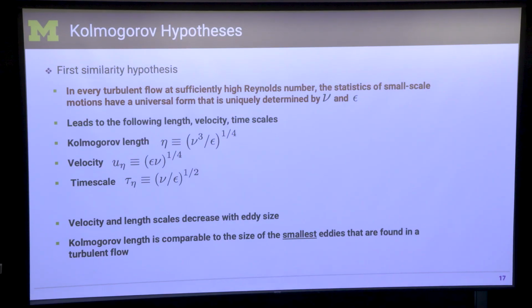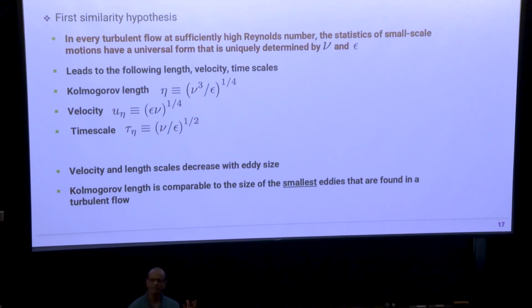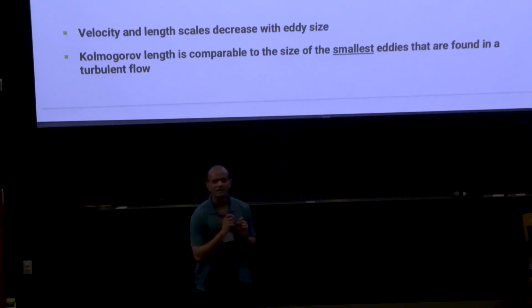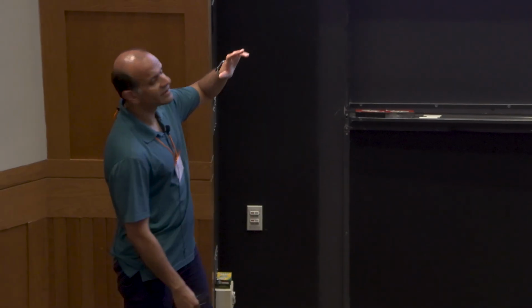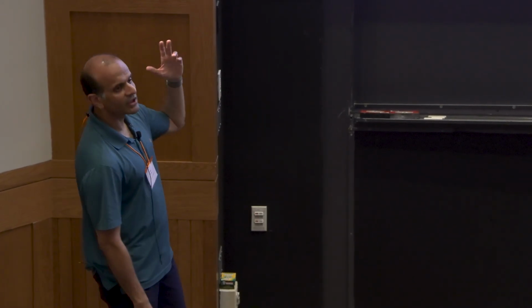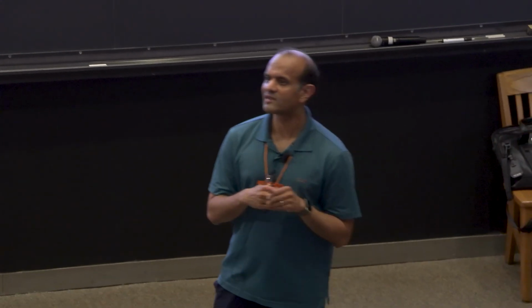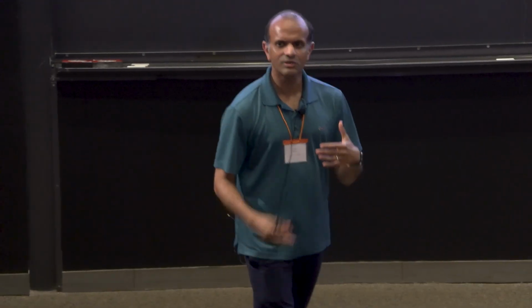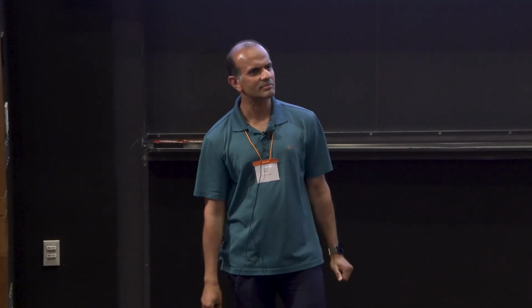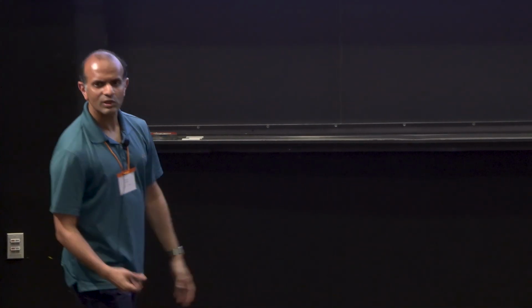So once you have this, that's good to know, but you cannot do much with it, right? So you need some quantitative tools you can have to say, okay, if I have to compare flows, what can I say about those flows? Reynolds number is a good way to compare different flows. You need some more features. And so he defines these additional quantities, and one of them is the Kolmogorov length scale. The others, to me, are not that critical, but the Kolmogorov length scale is the bane of simulations. If you don't have Kolmogorov length scales, and if you don't have these features, doing the simulations will be a lot less expensive. Okay? So the Kolmogorov length scale, we talked about these eddies breaking down.